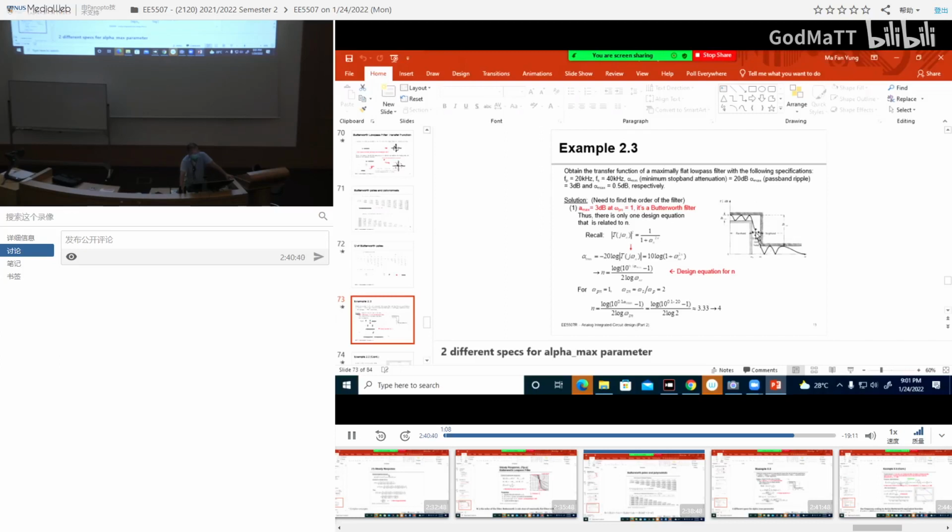So I define what the transition region of the filter is. And we know from the previous plot that the sharper the transition, the higher the filter order that's needed. So with this, we should have the information we need to find what Butterworth transfer function we need and what the order is.